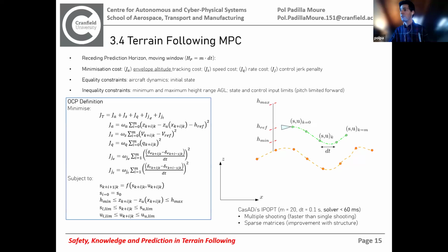If we put all this together through CasADi, as I've said, when compiled, we can get assured compute times below 60 milliseconds, and for a 10 hertz control loop, that would be enough. But recently, I've gotten compute times of just 10 milliseconds, and this is on a very simple CPU chip, an Intel N200. That's just about 1 gigahertz clock speed. So it is quite impressive the optimization that one can reach if the MPC is well defined and the variables are properly structured.